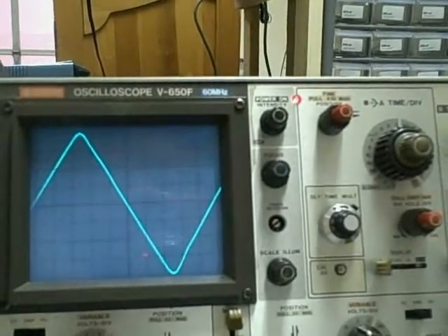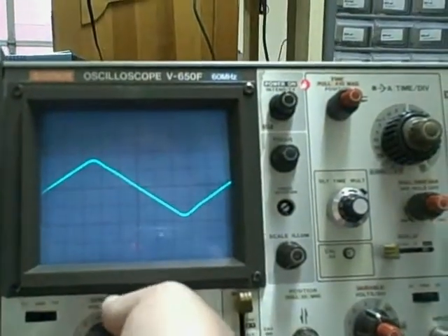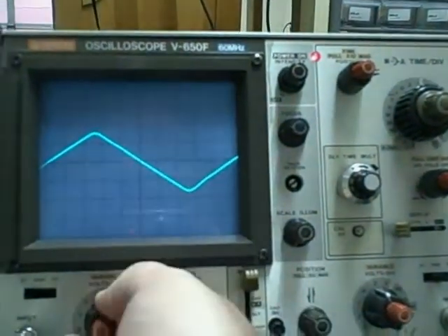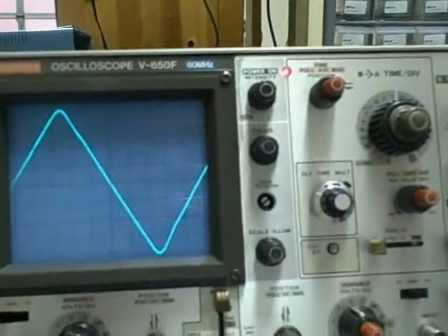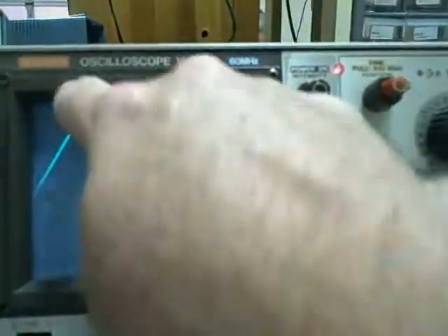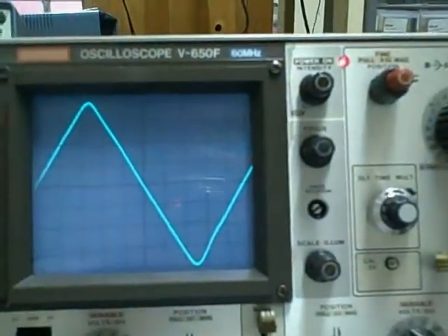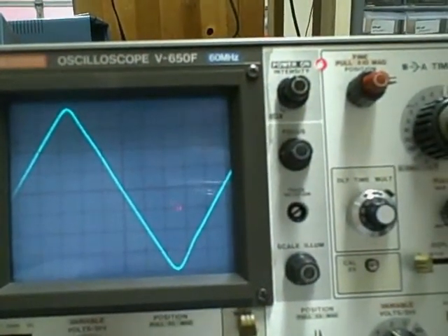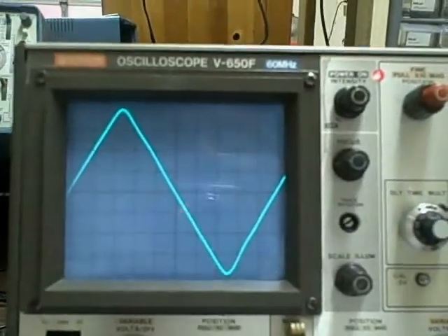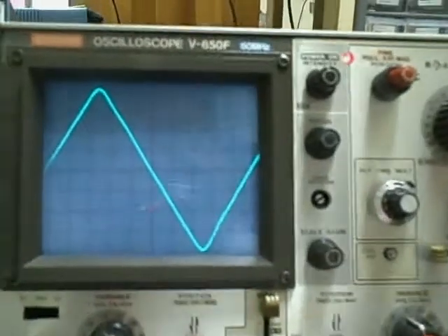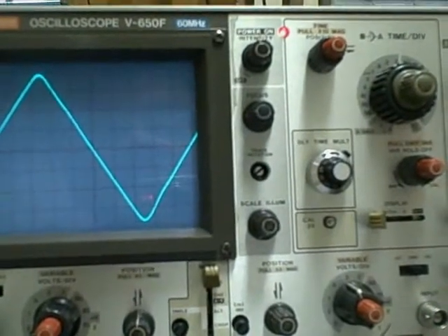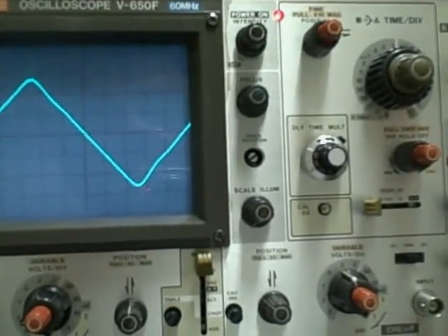We're displaying 8 volts peak to peak. Here I'm going up 5, up 3 more, that's 8 volts. And there's our 8 volts. So we are linear at our fastest speed, and our time base is accurate at our fastest speed, and we're going to reduce our voltage again so that we can get down to the next level.